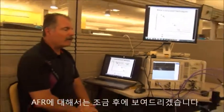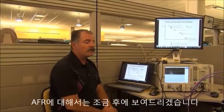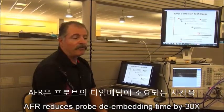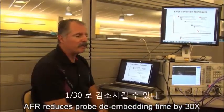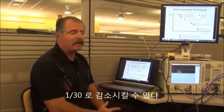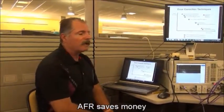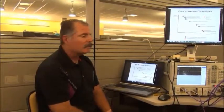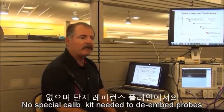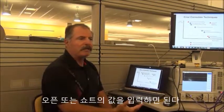There are many different ways to skin a cat. The way we're going to do it today with AFR is going to probably save on the order of 30 times the amount of time spent. A TRL calibration kit, once you design it, fabricate it, and use it, is going to cost, who knows, $5,000 to $10,000, and the measurement will take maybe a couple hours. With AFR, you don't need to build any special cal kit. All you need is to put an open or a short at the reference plane that you want.